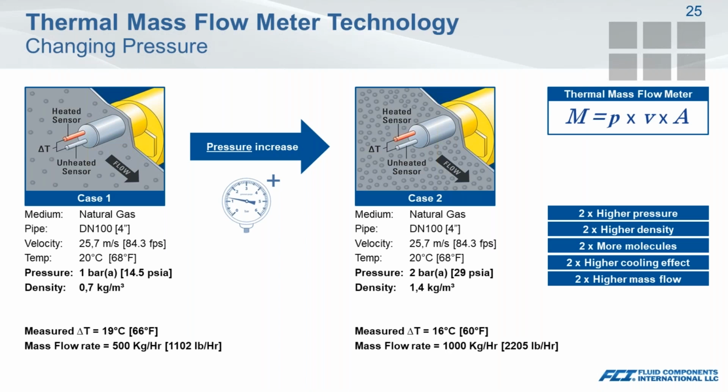And again, tying back to our basic equation, these changes in density, the cooling effect of having more molecules flowing past that sensor, or fewer molecules if the pressure drops, is all taken into account in the thermal mass flow measurement.